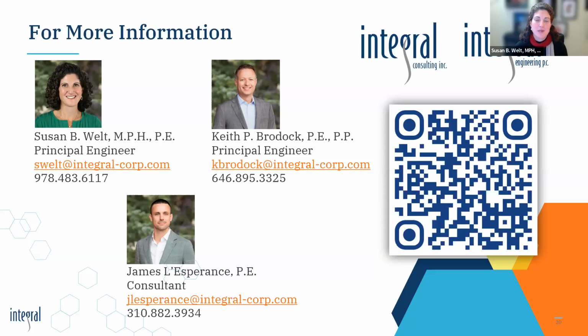But many times we're developing a vapor intrusion system because of the impacts in the groundwater. And if the water rise is just groundwater, not just because of sea level, then the compounds that we're trying to address, we also have to think about being in contact with the vapor barrier. Is the vapor barrier compatible with that chemical? Can it withstand what's going on there? Do we have to build a system differently, with floating systems, even aerated floors or something else to create that void space?